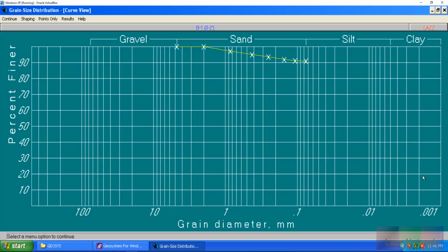And the idea is that with your hydrometer tests, you're taking a hydrometer reading at timed intervals. So you might take one at 1 minute or 30 seconds. If somebody's a monster, 30 seconds, that's so hard to do. 1 minute's not easy either, but you might have maybe 30 seconds, 1 minute, 2 minutes, 5 minutes, 15 minutes. So you're taking these readings all the way until usually people are satisfied after 24 hours what your material is going to be.